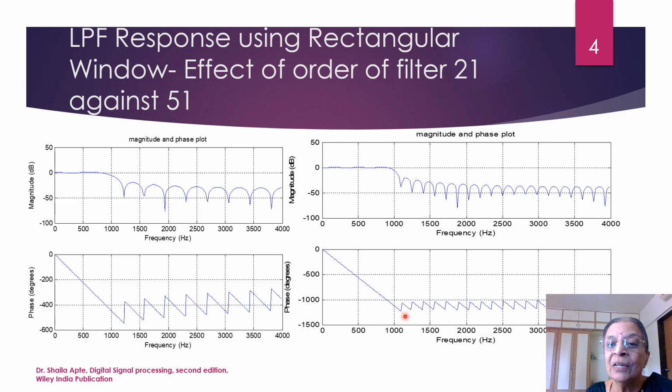This is the main advantage of using the FIR filter, which is a linear phase filter. And this is the requirement for the speech signal. So normally for speech signal, we use FIR filter design rather than IIR filter design. Because we'll see that in case of IIR filter, you cannot predict what will be the phase response, because it is not having linear phase. Now in this case, because of the linear phase, no phase distortion is introduced in the output of the signal when it passes via the filter. So that is the main advantage of using the FIR filter.